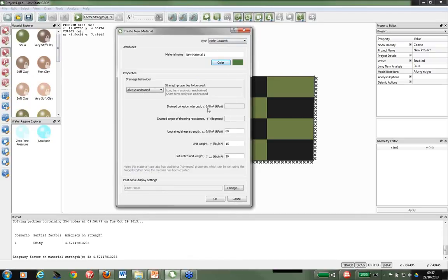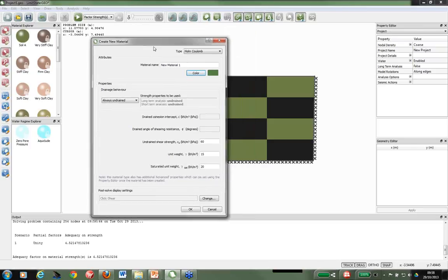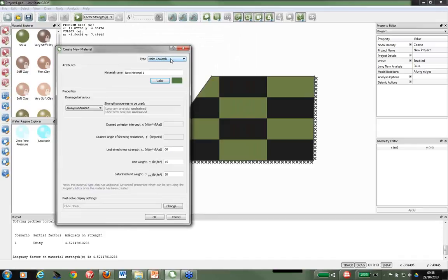So we're using C-phi and Cu, and we're using Mohr-Coulomb for C-phi materials, and essentially Tresca for Cu as our failure condition in those. So it's the standard sort of models for soil behavior, but you can modify them as we've just shown by adding a cutoff material to eliminate tensile strength in the solution.